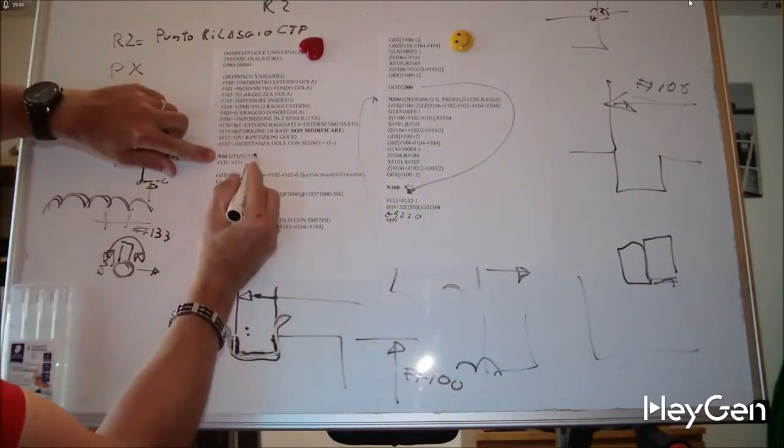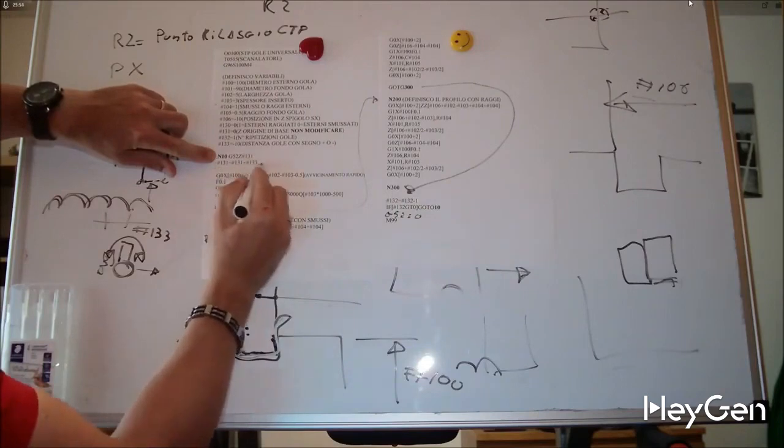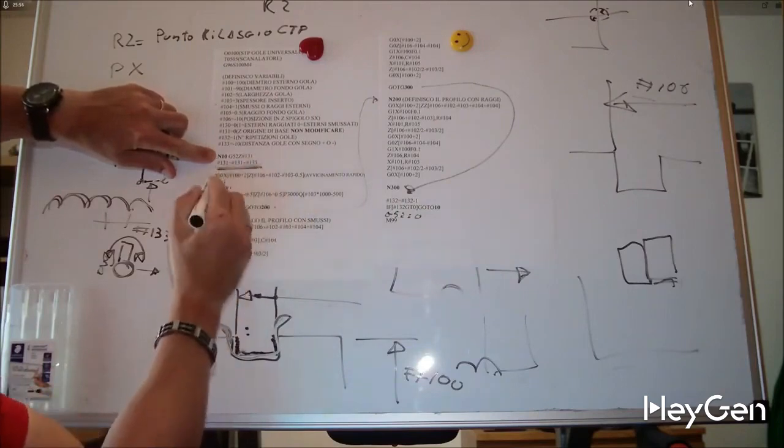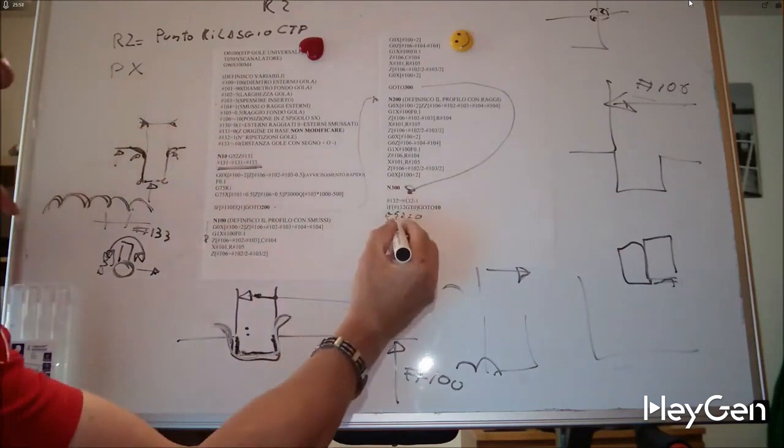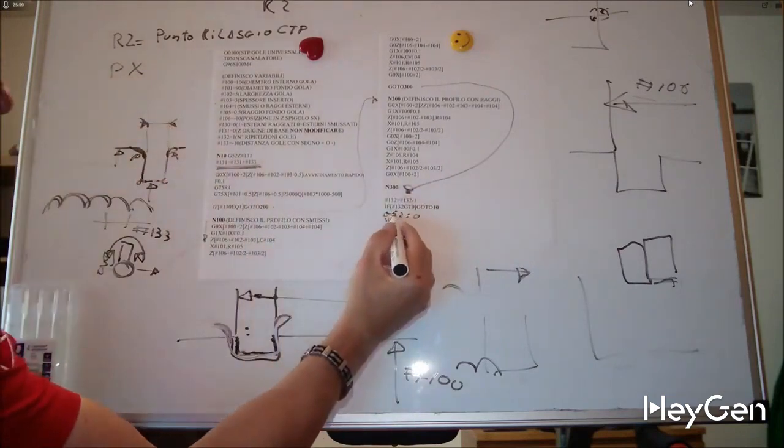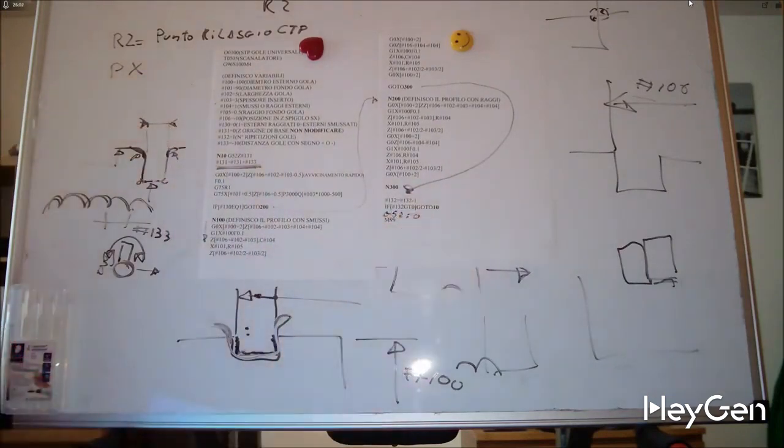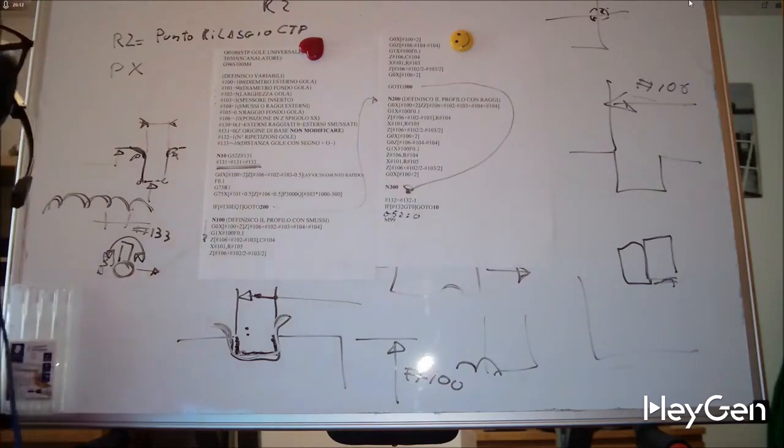That is my origin, calculated according to this little equation. If it's equal to 0, I go to M99 just to be thorough. I set G52 to 0, and there we have finished our program, allowing it to make choices.